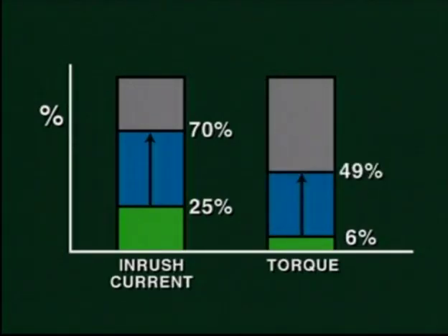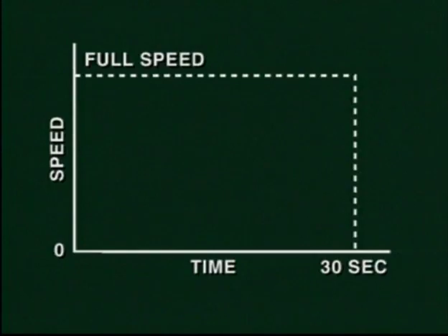These controls can be adjusted in the starter by modifying the potentiometer or a digital setting. The acceleration to full speed can be ramp adjusted from 1 to 30 seconds.